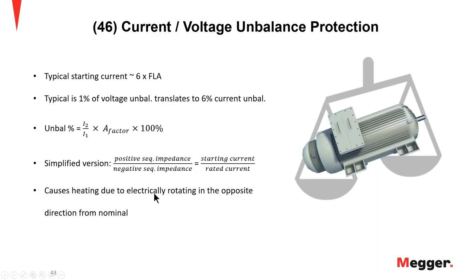We also want to make sure that the relay settings account for the negative sequence currents that could be present but not coming from the motor protective circuit. This could be an external component that could also be seen by the relay. Therefore, time should be allowed for the appropriate protection to clear it. This will also help prevent unnecessary negative sequence currents from being introduced into the motor circuit and overheating the motor. That's unnecessary, because we don't want anything to affect our motor that we're trying to use.